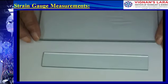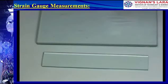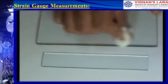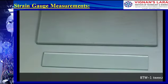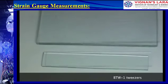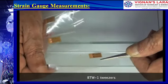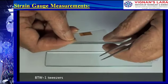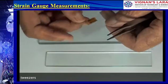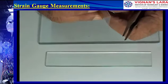A glass plate is used as a working surface for handling strain gauges. The glass plate is cleaned with a few drops of neutralizer to ensure that it is free of dirt or dust. To handle a strain gauge safely, a blunt tipped tweezers such as the BTW-1 is used to remove the gauge from its packing and lay it on the glass plate which is cleaned with neutralizer, making sure that the top side of the gauge is facing up.